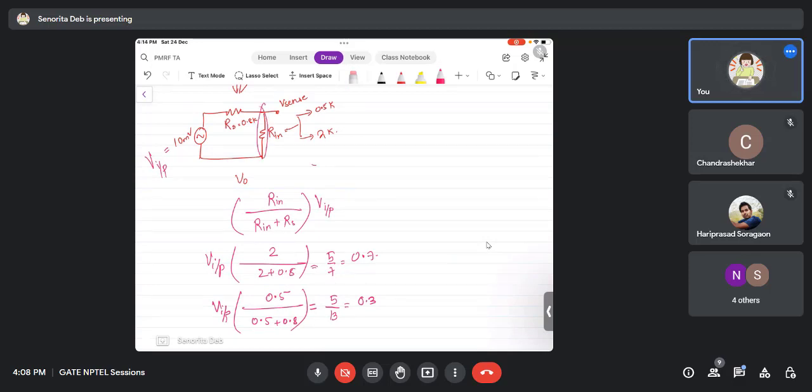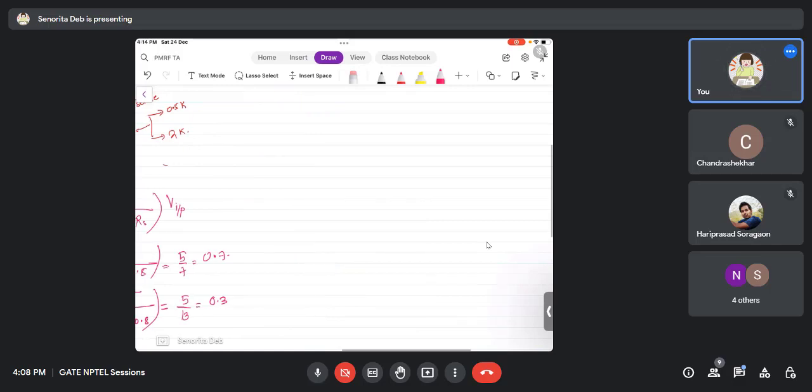So now you see, depending on what your amplifier's input resistance is, 2k and 0.5k, what voltage the amplifier is seeing depends on that, right? So even if the microphone is the same, and the mic is sending out the voice, the 10 millivolt signal, since the amplifier's input resistance is 2k or 0.5k, which is less? 0.5k is less.